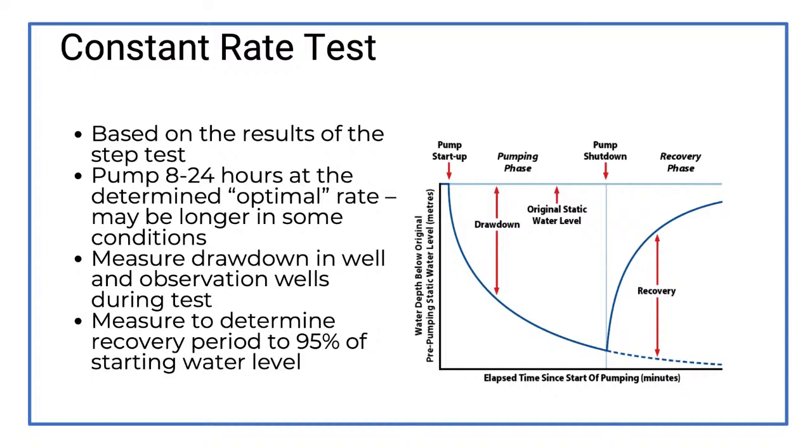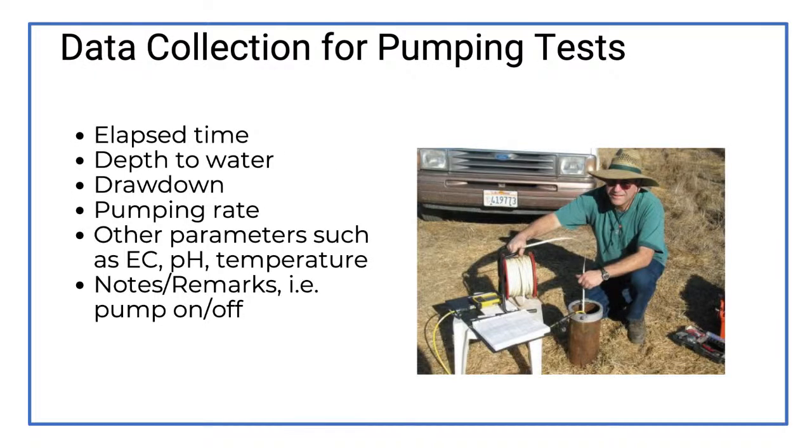So once again, you're going to do drawdown until you hit steady state conditions, and you're going to do the recovery test. Data collection: elapsed time, depth of water, drawdown, pumping rate, other parameters such as electrical conductivity, pH, and temperature. Sometimes we'll measure those.